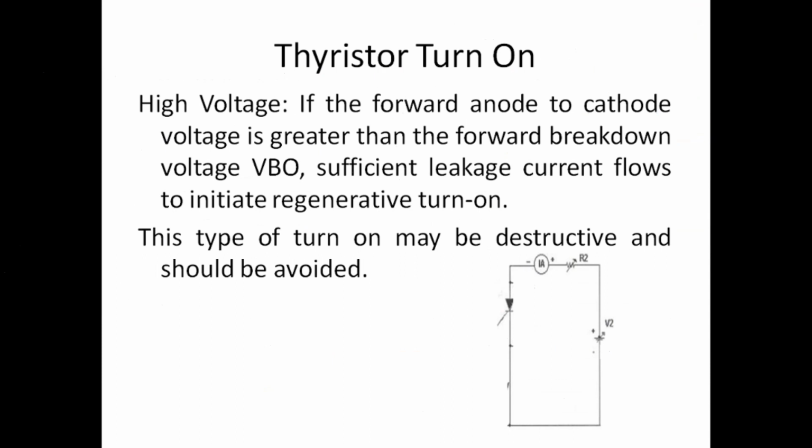SCR will get damaged. From here onwards we need to understand that for a proper operation of SCR circuits, we use gate terminals. Whenever we need to turn on the SCR, we should apply the gate current. Then only the SCR should turn on. Unless we apply gate current, it should not turn on.